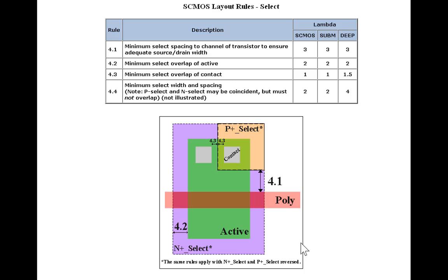So now it is much more time efficient. In the old days, you draw a lot of things, and then you say I run DRC, and then it will show you 157 violations. Then you need to move them, etc. So in those days, we tell the students that you don't draw a lot of things. You draw just a few polygons, and then you do a rule check. You draw another few, and then you do a check. And then you can save a lot of time.